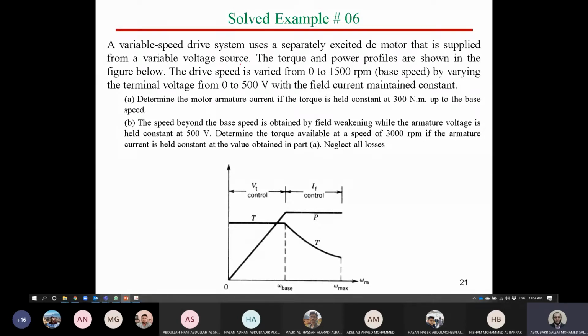And the task of the power electronic converter is to achieve the certain level of voltage, or whatever the value of V, if it is DC or AC according to the motor, or frequency if it is an AC motor, in order to control the motor speed. So here in case of DC motor, the supply voltage of the drive will definitely be AC, and the output of the power electronic converter should be suitable to the DC motor, which should be a variable DC supply.